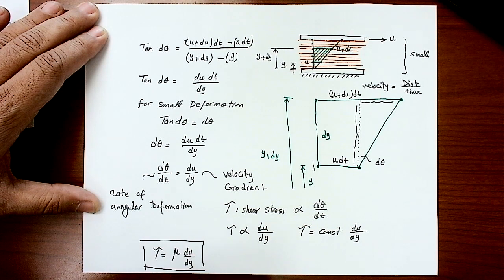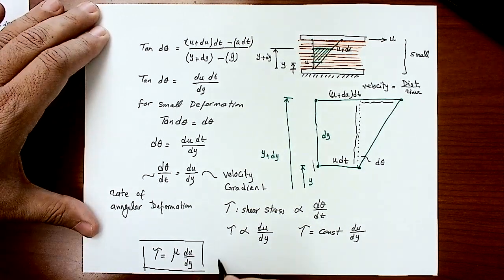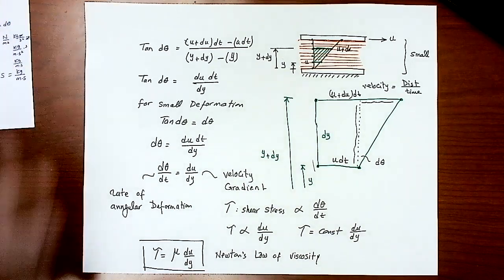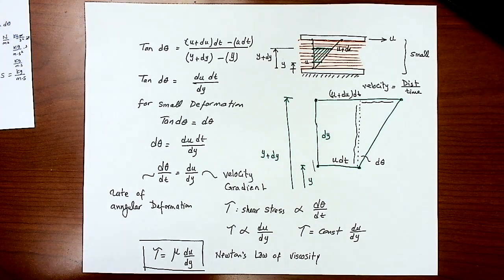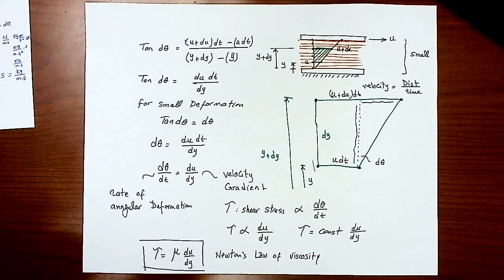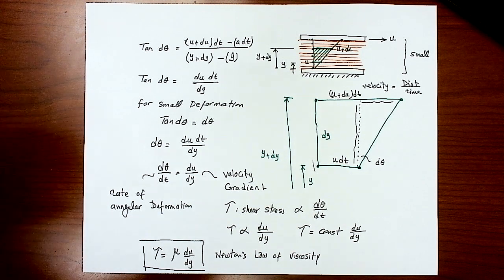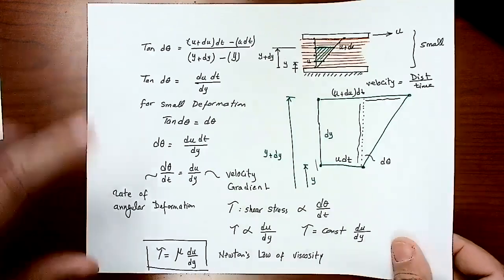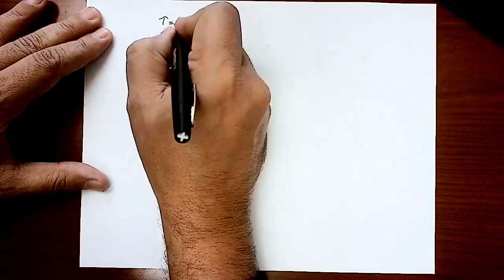And we're going to actually highlight this relationship, and this is called Newton's law of viscosity. And this is a very important fluid dynamics relationship. So the shear stress applied to the fluid to cause deformation is equal to viscosity times the velocity gradient of that fluid material. It makes a lot of sense. Viscosity has to be included in the motion because it's an indication of the resistivity of that fluid to move at all times. So that's Newton's law of viscosity. So if you give it more focus here, again, I'm going to write it down here. So the shear stress equal to mu du by dy.